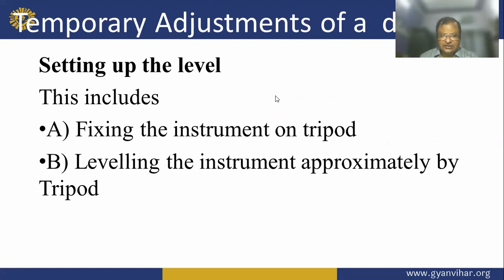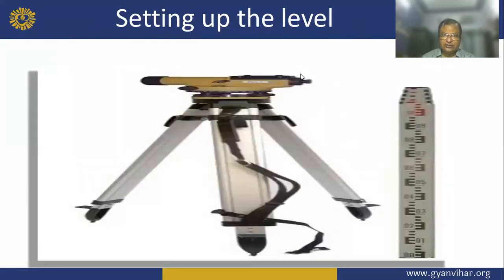Setting up the level includes fixing the instrument on the tripod, leveling the instrument approximately by the tripod, and setting up the level machine.